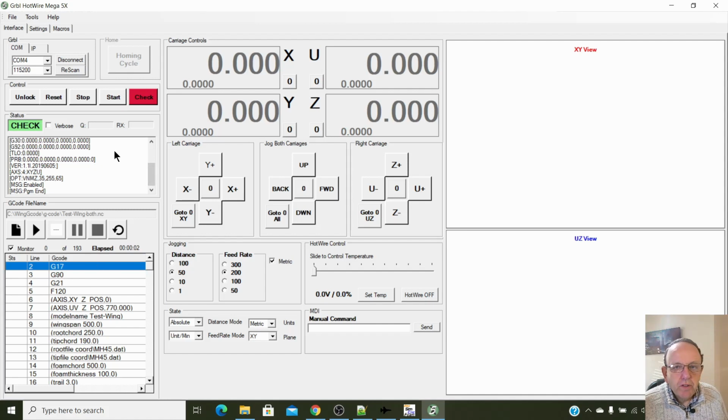This newer version will also... The GRBL foam cutter doesn't support every single G-code command because it's such a tiny machine. It hasn't got the memory and processing power to do that. So there are some G-codes that are not supported. In this newer version, if there are any of those unsupported codes in there, it will just ignore them, and so you shouldn't get any errors.